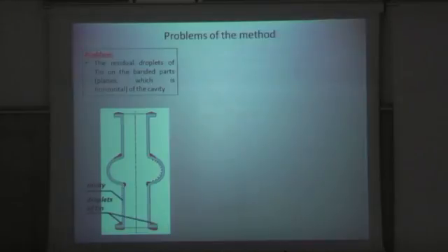But there are a few great problems of this technique. First of all, the problem of the residual drops of the tin on the bent parts of the cavity. You can see it on the picture. Tin is marked by red color.